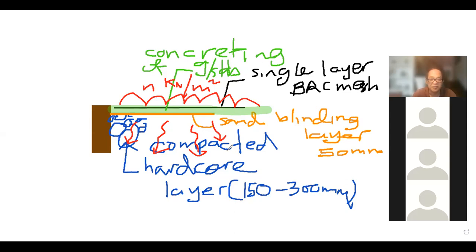So this sort of construction is very much suitable for cut areas only, where the soil is considered a good soil. It is a hard, good soil, tanah yang keras, tanah yang bagus, with high bearing capacity, and therefore there is less possibility of settlement. Remember, settlement is part of the soil's characteristic, settlement of the soil.